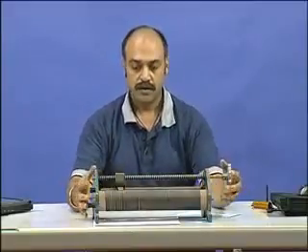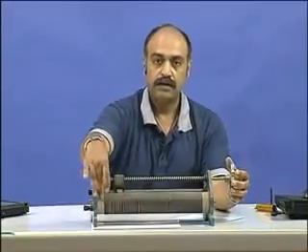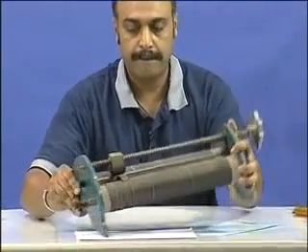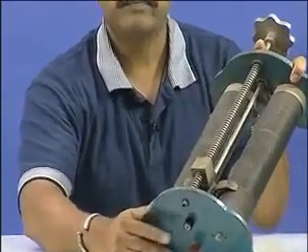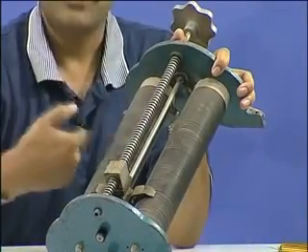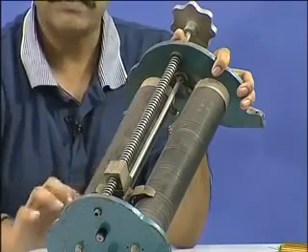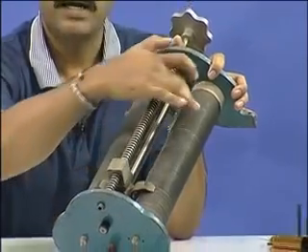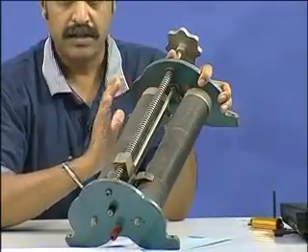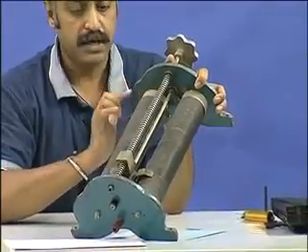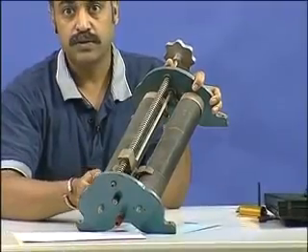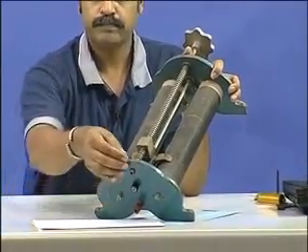You see that there are 2 cylinders. Are you able to see? I will hold it like that. There are 2 cylinders composed of wire wound wires. This gives the resistance. They are connected in parallel such that they can handle higher current and therefore more dissipation. These can handle something like 25 amps and they are 2 ohms, which means something like 1250 watts.